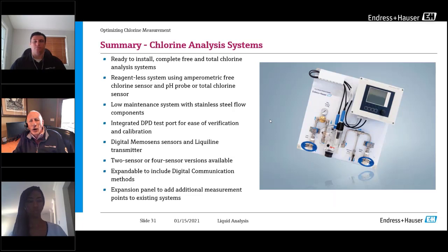Or are they wanting to take that water and make sure that it's adequately been chlorinated for disinfection, in which case they would probably want to add more chlorine to it till they got to a point where they actually had some free chlorine, not just chloramines? And at that point, they might want to measure free chlorine, or maybe they want to measure total. It depends on what they need to be measuring going out of their process.